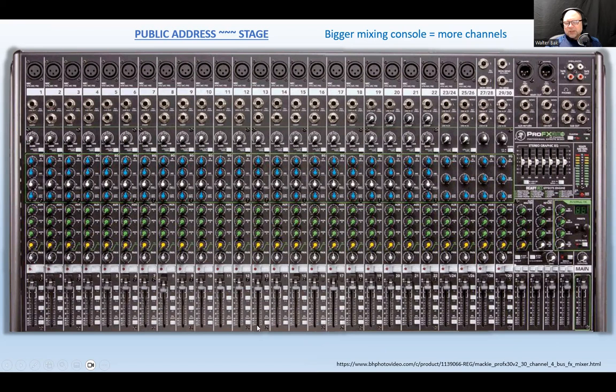So you can group some of the channels, for example, if you're miking the drum set, which would be about 6 to 8 microphones. You can adjust the volume of each microphone applied to the drum set, establish proper balance of those microphones, and then assign them to one of the groups. So if you want to raise or lower the volume of just the drums, you can have one knob just to do that. It's a convenient thing. Just an example of why the groups are being used.